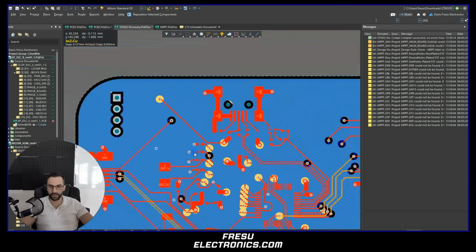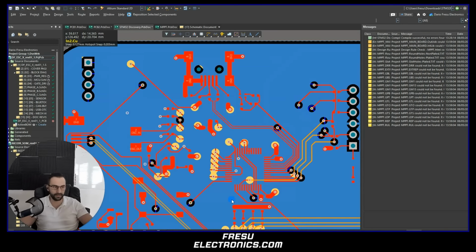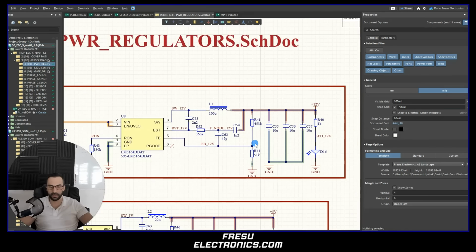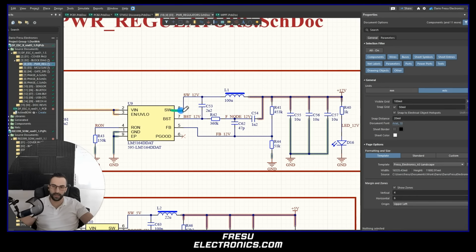Now let's go to problem number 4, which is large current loop size. This is a problem that we can see quite often in switching regulators, and this is going to create, of course, EMC issues. So we want to keep the loops as small as possible. To show you a loop, I will show you this example here. So what do we mean with large loops? What's important for us is this switching node. The switching node in here is where we have this inductor, then the feedback to control the output, and the output capacitor. And then in here, we go back to the source.